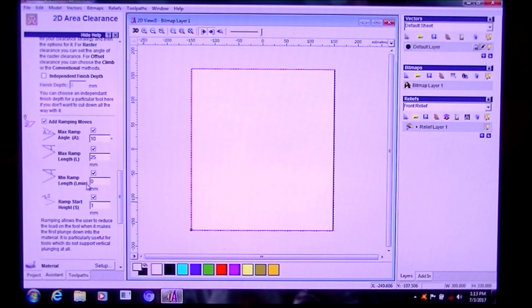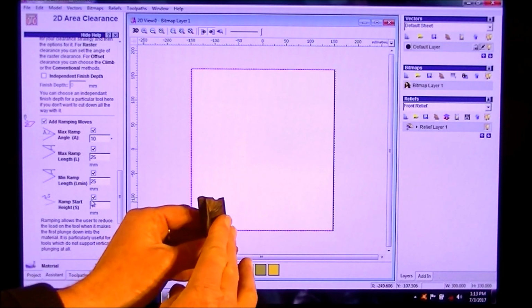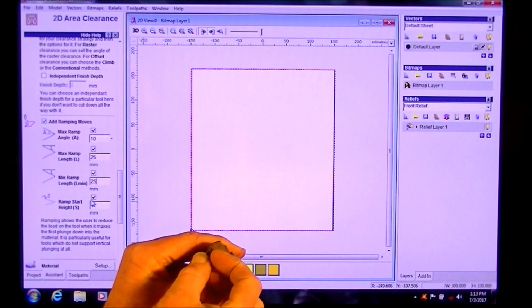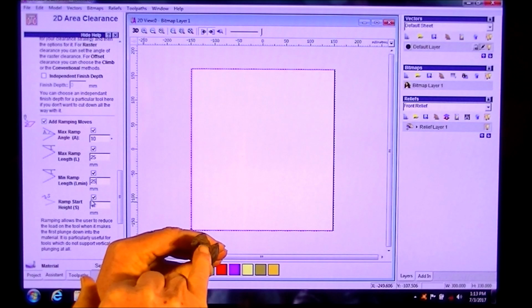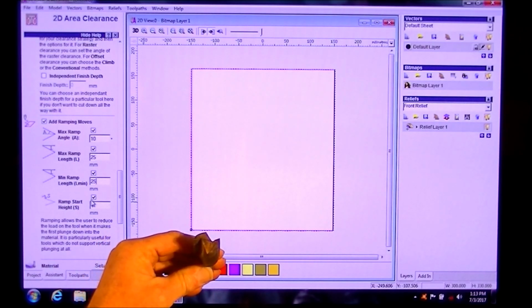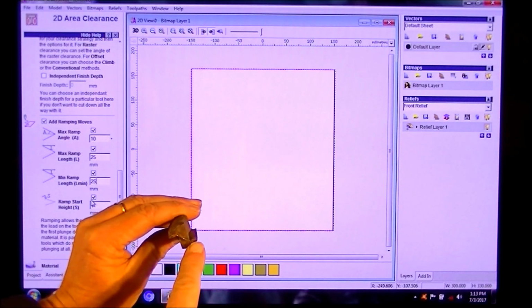25. I would say, no, we want 25 millimeter. We don't want a minimum, because what happens is, the cut-in surfaces on these particular rotor tools are there and there. So in the middle here, you're just relying on that piece of metal there to remove the material. So you want the cut-in surfaces to remove it.